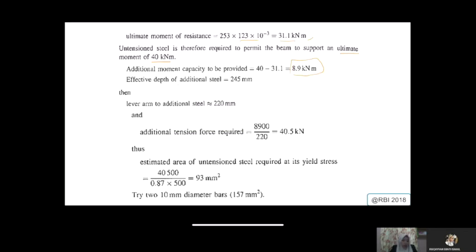Basically, you can put it anywhere you like, but normally it will be slightly above the tendon, and of course you have to justify it. You also have to consider the allowable spacing based on the standard, like when you do the checking for spacing, whether it is okay or not.